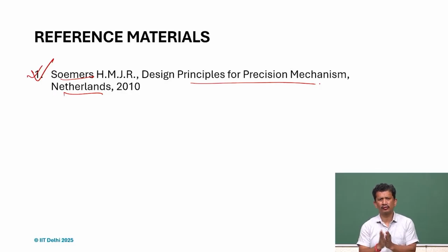For those kinds of applications, we may need very high stiffness values. But on the other hand, suppose it's a very sensitive piece of equipment designed for different applications, or suppose we want to support something and don't want to transfer any vibration or noise from the ground, then it has to be supported with very low stiffness values.